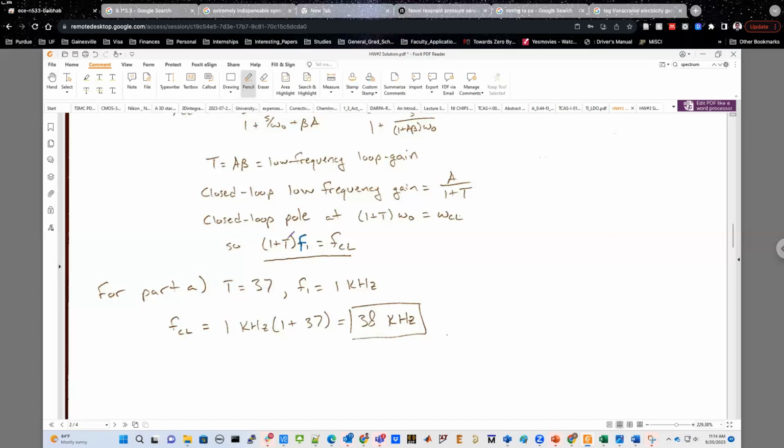Now in open loop, this is how your gain and the bandwidth will look. In closed loop, you'll reduce your gain by 1 plus T0 times, or loosely speaking by T0 times. So your bandwidth will increase by T0 times. Strictly speaking, 1 plus T0 times. So that's what you'll see. Because you know what your T0 is, you'll know what the increment in the bandwidth would be. So the bandwidth will be increased by 1 plus T0 times. So that would be your closed loop bandwidth.